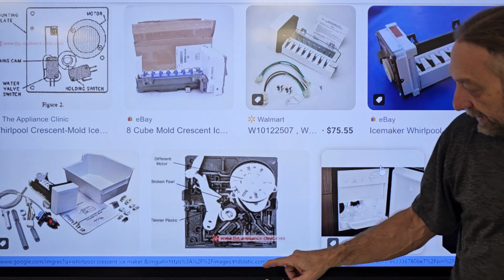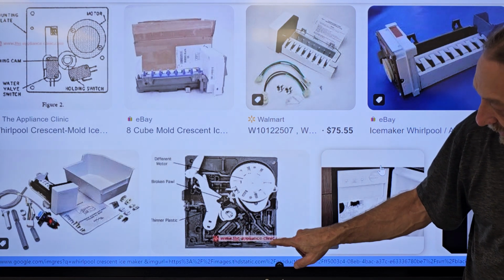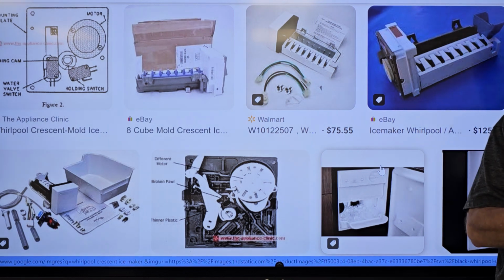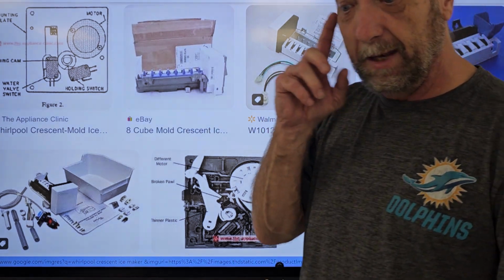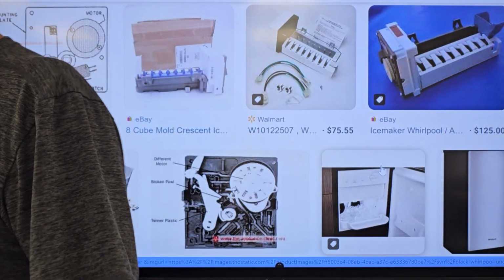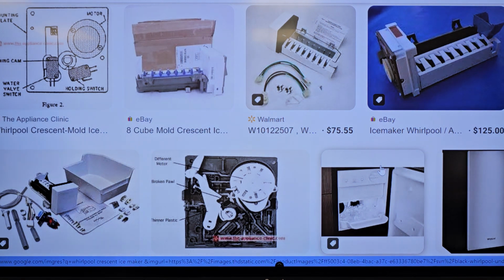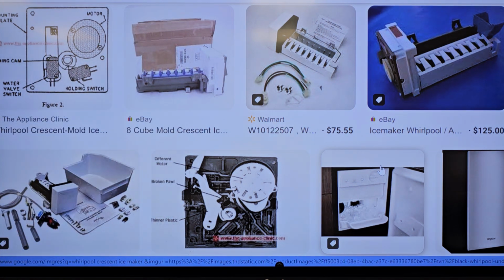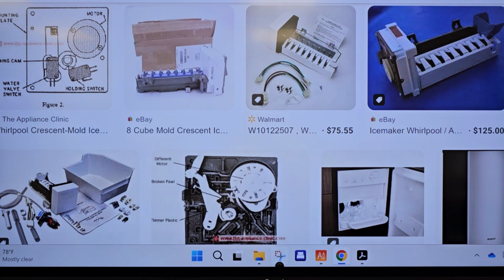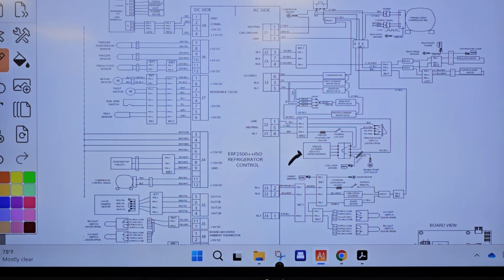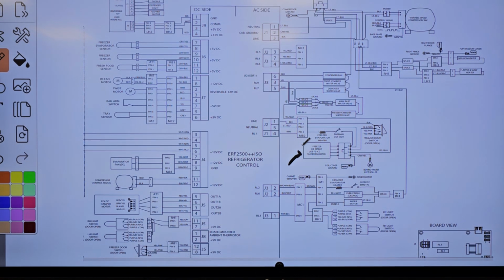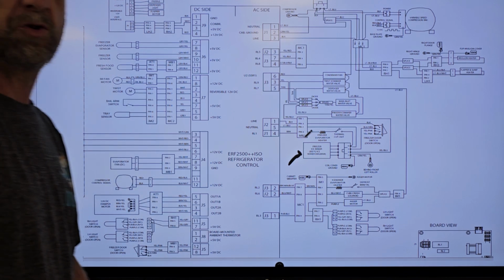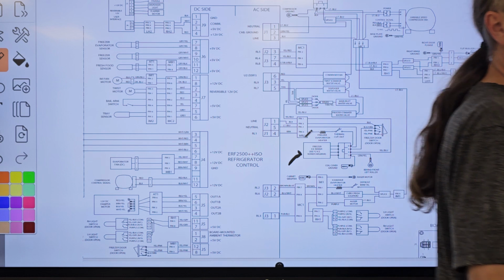And this one here had a plug right there that plugged into where the wiring harness was. And it would burn up and go bad. And they had other problems with it as failure. So you'll find manufacturers will have one or the other in there. But going back to the diagram we were talking about, this here is not the ice maker that's inside that fridge. It's not the flex tray ice maker. So where is the flex tray ice maker?